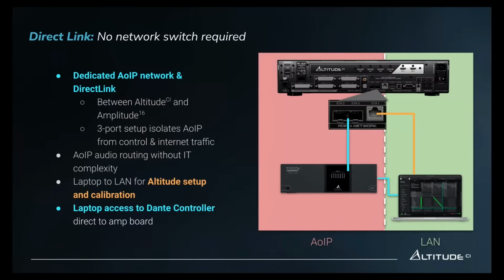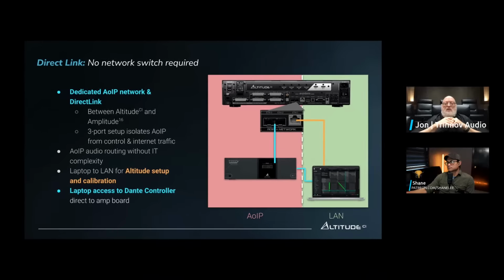One thing you need to know is that audio over IP, whether it's Dante or AES67, needs to be kept separate from the more general traffic on your local area network to make sure there aren't data collisions that might cause an audio dropout or other problems. Now, because we knew that not every person installing one of these things was going to be a network engineer, we've made doing that, at least in modest systems, pretty darn easy.